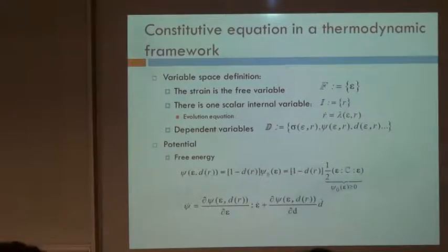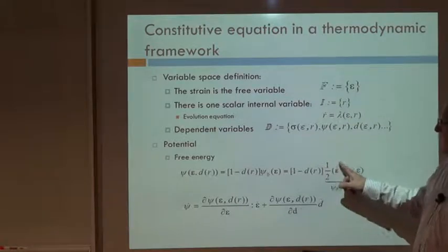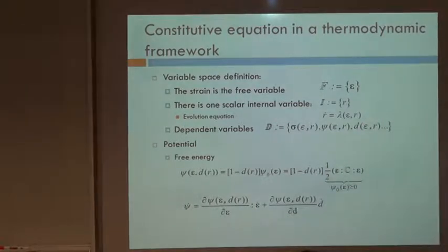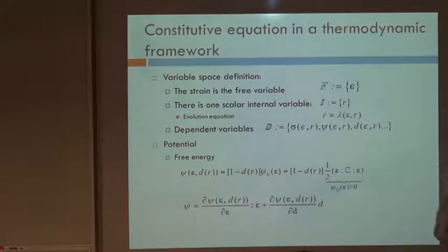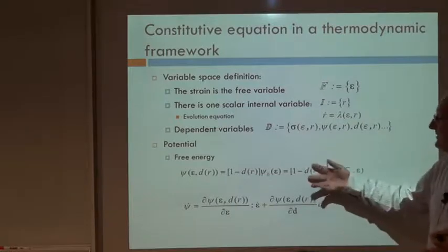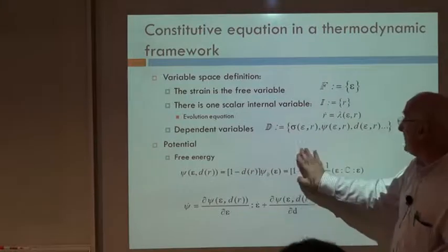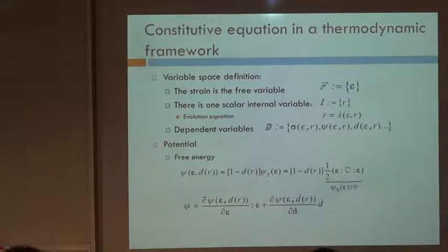But then we affect that capacity of storage of energy of the material by the factor 1 minus d. When d is equal to 1, that means completely broken material, there is no capacity to store anything. But for d equal to 0, we have the same capacity as any elastic material. So let's try this kind of definition of the free energy. It's just the one that we would have in an elastic material multiplied by the factor 1 minus d.